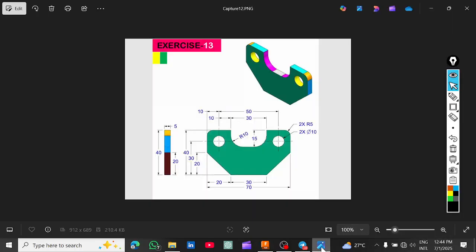If you notice in our design, in our sketch, in our design example, there we have some fillet. You can see arrow meaning radius of 10 millimeter at this end and radius of 5 millimeter at this end. 2x means that it's two separate edges, meaning that you add it in this edge and this edge. So it's representing these two edges. So you add two 5 millimeter radius fillets here, rounded edge is 5 millimeter. Here is 10 millimeter round edge. Here is 5 millimeter round edge.